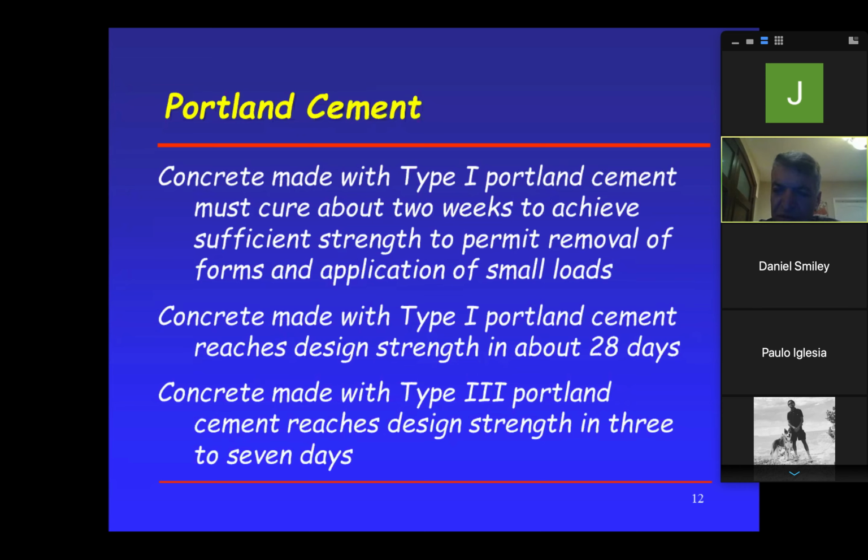But just to convey my idea. In those post-tension beams, we put something that looks like a rope, but it's a steel rope, strands we call them. And we wait from Thursday till Monday. On Monday, the contractor will come, and you lay these metal ropes in it. They are anchored at one end and loose at the other end.